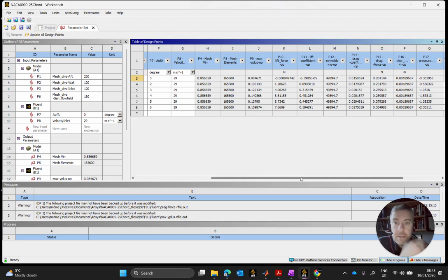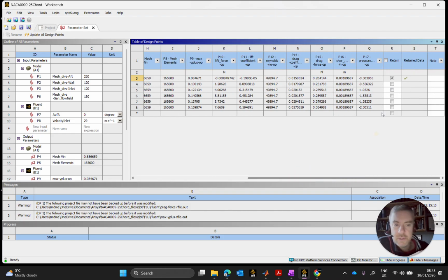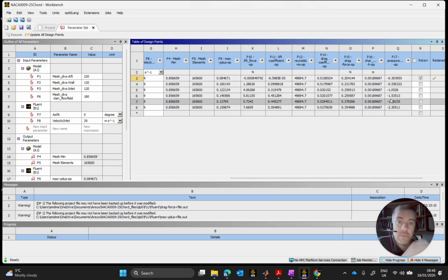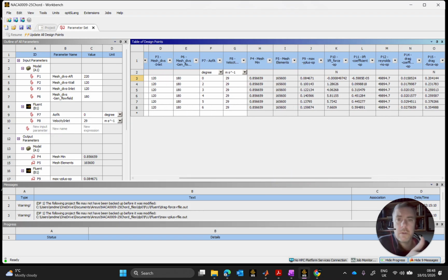I could also, as I said earlier, increase the number of convergence iterations before stopping the solver to give it more time to find its converged location. And finally, what I definitely should do, just for robustness and thoroughness, is to put in pressure output or lift coefficient or indeed drag coefficient in as a convergence condition as well, just to make sure that one of the critical metrics is also met, or all of them.